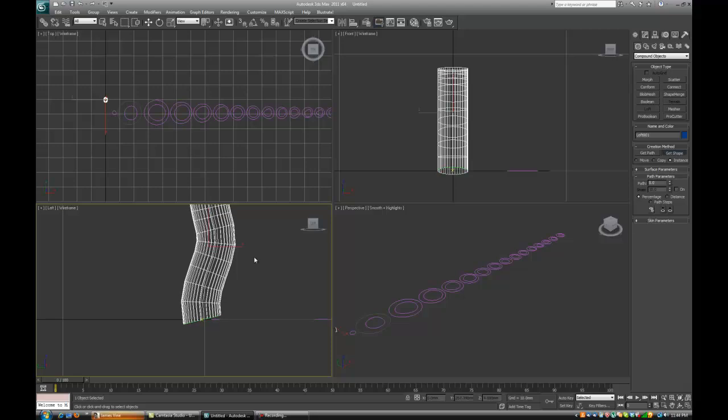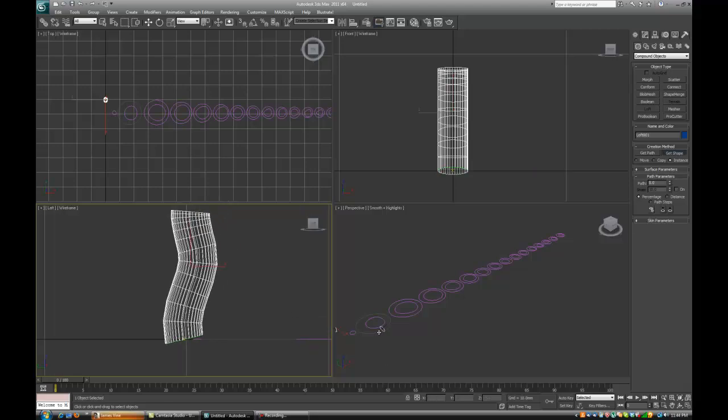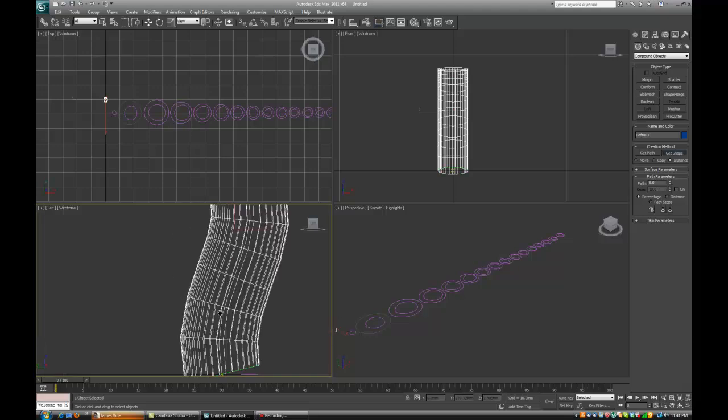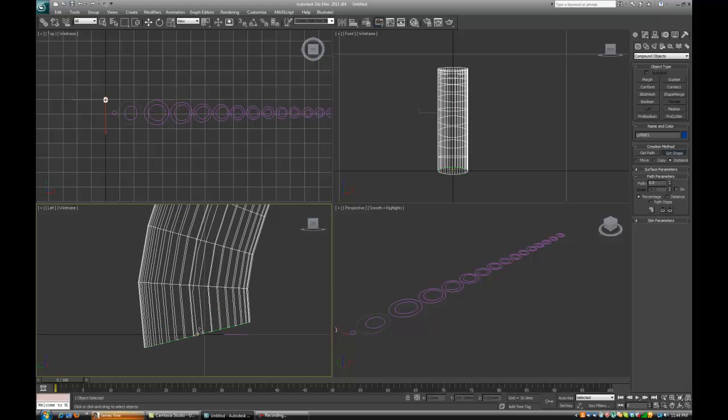Now, to put in these extra outer curve sections onto that line, we need to change the path parameter at which they're going to be placed. To do that, you can, if you see this little yellow cross, when I move this path parameter from 0 to 100, it's going to move to the certain percentage where that is on the line. So in this case, I've got 1, 2, 3, 4, 5, 6, 7, 8, 9, 10. We'll just do 10 curves for this example.